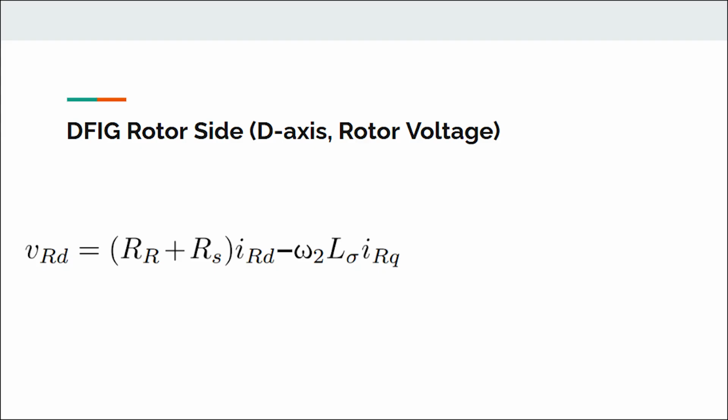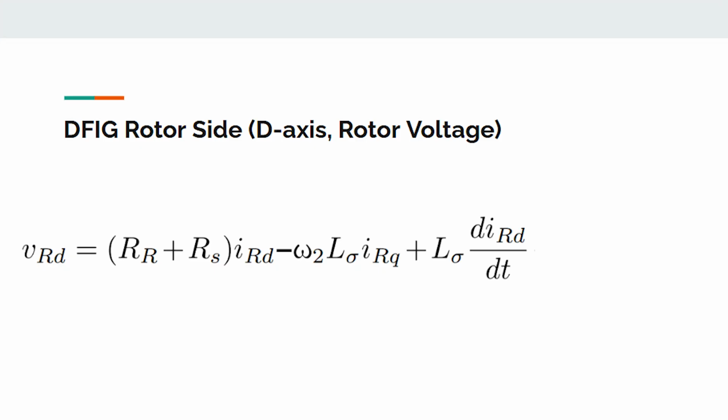The current at the rotor must then overcome the leakage inductance seen at the rotor to adjust the reactive power desired. Like the equation V_RQ, the voltage across the rotor in the d-axis must apply enough current over time to overcome the inductance of the rotor. This means more voltage would be applied to the rotor in the d-axis.